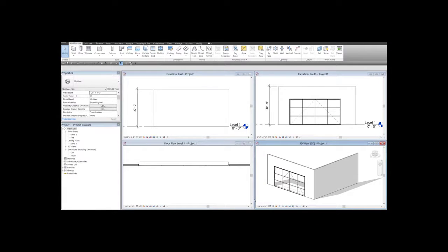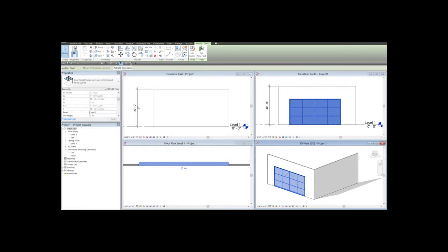If the door becomes too large, you might be exceeding the maximum size for the panels in between the mullions, which is 60 inches. If you click on the family and read the instance parameters, you will see that there is a warning about that dimension being too wide.